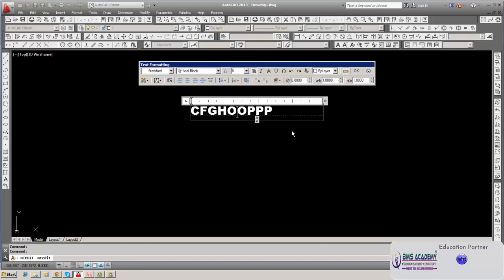So what we have to do is, we just fix up the scale factor first. See the drawing size, what is the scale factor you are going to apply, you decide. After deciding the scale factor, you have to select the scale factor for the letters. Suppose you want letters to appear as 5 mm size in the actual drawing sheet.